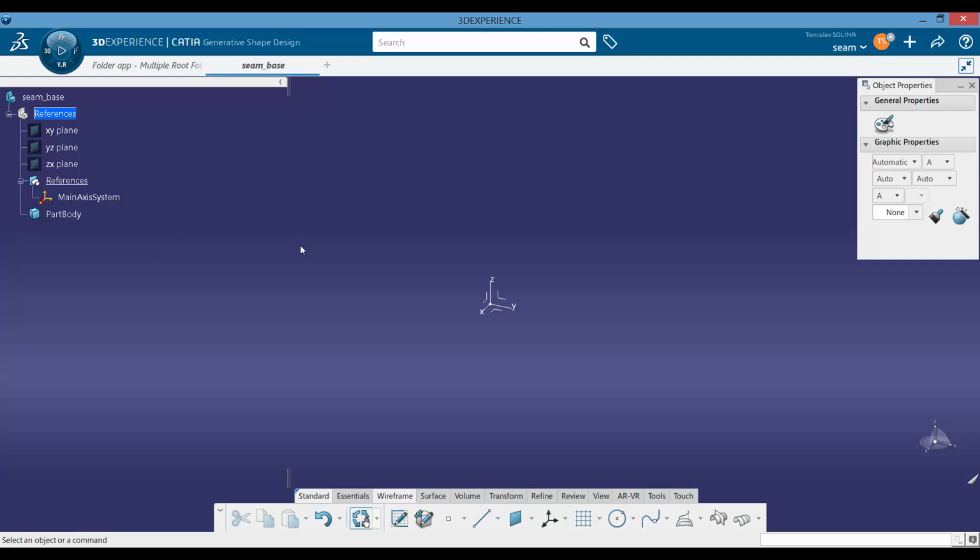So, for instance, functions like edge fillet or functions like trim are actually very bad for your models, and they are very unstable functions, as their definition can be modified very easily if you have multi-patch surfaces. So it can happen that they lose orientation, that they lose the reference of the edge that was selected, and similar. So we will avoid using those.